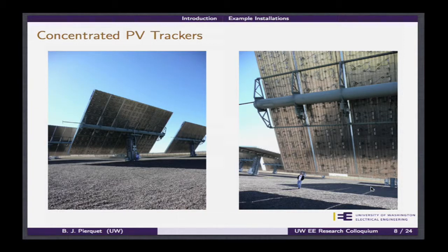These are massive solar trackers. In these cases, they actually happen to be concentrated photovoltaics. And so they actually take these trackers and they move them along with the sun. I believe these would be a 2-axis tracker, so they can actually change with the seasons as well as the day-to-day variations. Most of these types of systems are actually based on the same mechanics that operate radio telescopes.